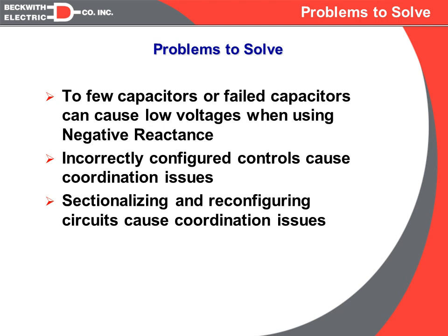The theory was that both the voltage regulators and LTCs and voltage control capacitor banks would all be looking at the same voltages, would all have the same rails or bands, so to speak, and would have different time delays to keep the coordination. The time delays were set to meet two requirements. Requirement number 1 is that they wanted the capacitor banks to operate and take the majority of operations, and that they wanted the capacitor bank furthest from the source to be the first to close and the last to open.